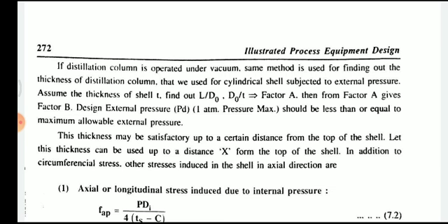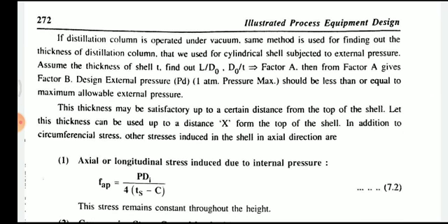It should be less than or equal to the maximum allowable external pressure. The thickness may be satisfactory up to a certain distance from the top of the shell. Let this thickness be used up to a distance x from the top of the shell.